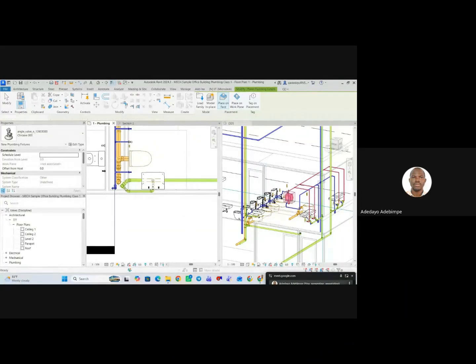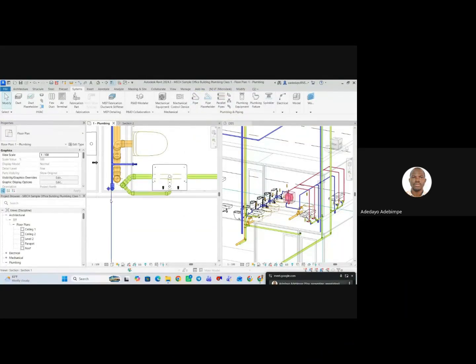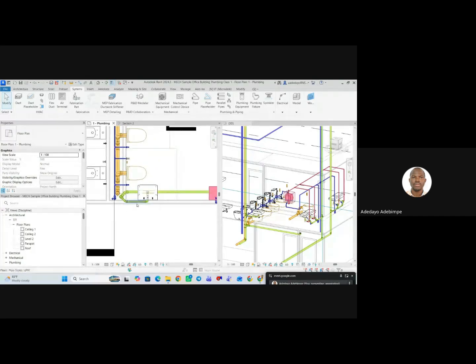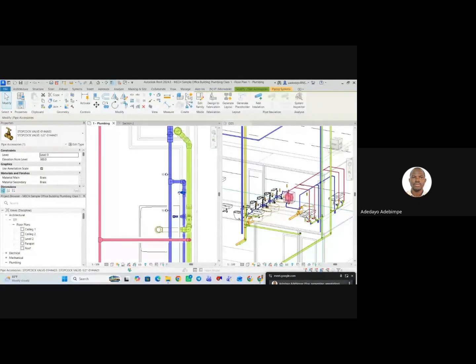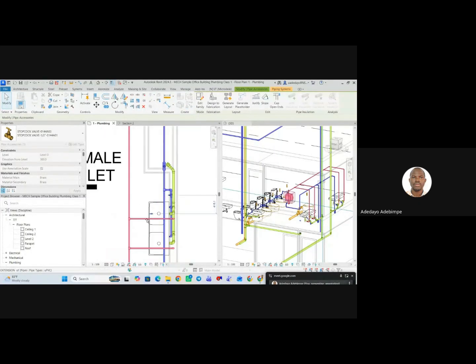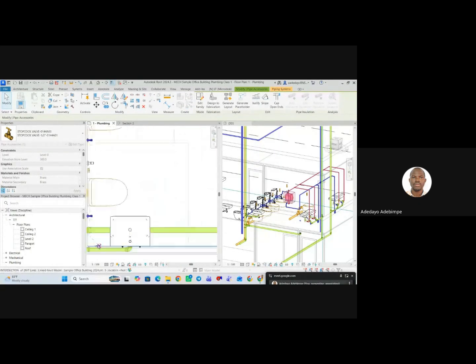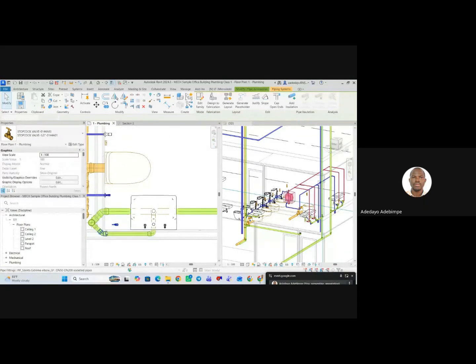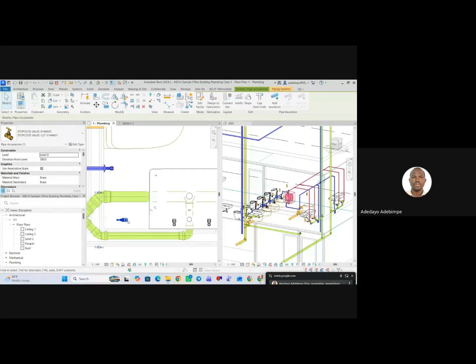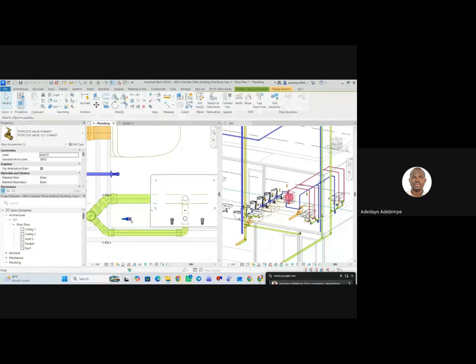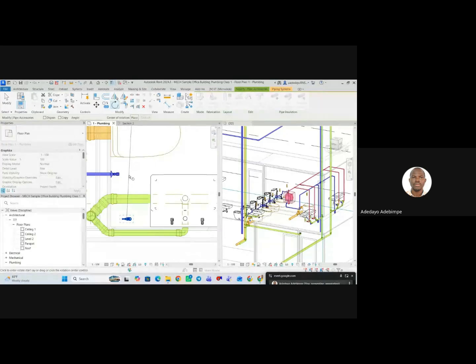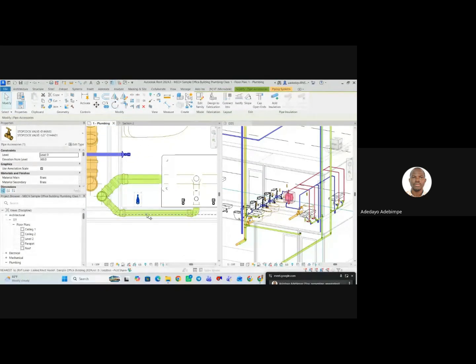Okay, so let's just quickly connect these remaining one wash and basin. Similar to before, I will drag this out to ensure I maintain all the levels, and I want to position this where I want it to. I'll right click on it and do RO rotate, drop, I'll do 90 degree, then move it into position.